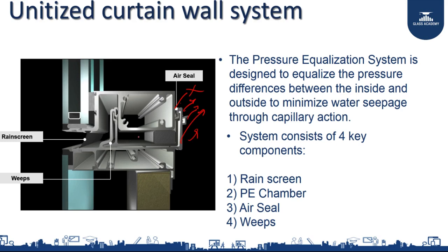Now, whatever water I have here, or even if anything goes wrong with this, water will start going in, because you do not have a proper air seal. So, this is what you call capillary action, because the air is sucking inside. It can raise several floors. I have personally seen a lot of failures where you can see water rising 2-3 floors inside a joint.